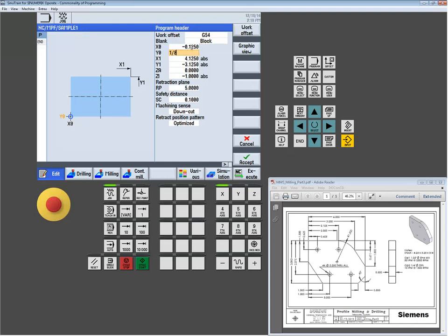You can also type fractions in here, and it will calculate it to a decimal equivalent. So I'm telling it that I'm starting an eighth of an inch off my upper left-hand 0. The lower right-hand corner, I'm telling it 4 1/8 over, so I'm giving another eighth inch of stock there. And down 3 1/8 on the bottom, because this bottom edge of the part is 3 inch.